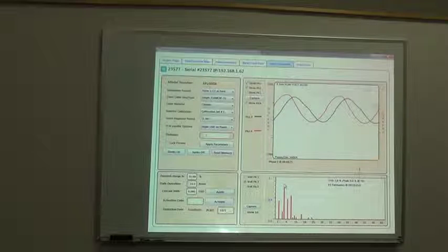That's what we do. But we don't specifically address the harmonics. We just mitigate it, make sure that we're not making it worse, and we do basically an inherent correction for the whole thing. Because you manage reactive power, it in turn helps a little bit. That harmonics that you see right now, 2.8%, last night it was 1.7% when I was checking that.